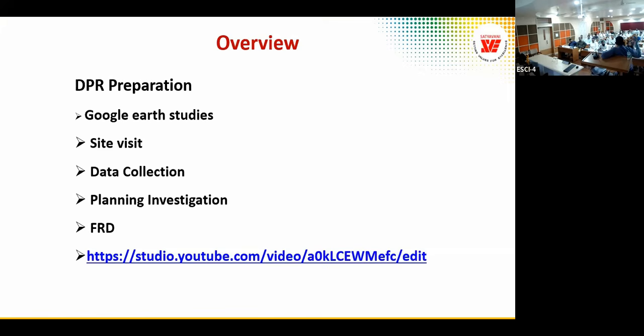Whereas when we started excavating, we found rock so hard that even a breaker or burner could not break it, and we can't do blasting because of the city condition. So we called the soil investigating agency to redo the investigation and do the RQD. You will be surprised, the bearing capacity recommended was 300 tons per square meter. Imagine the cost difference between 75 tons and 300 tons, four times.